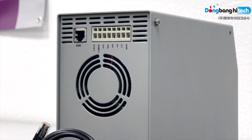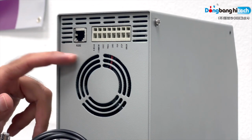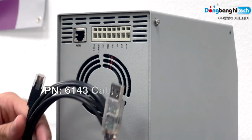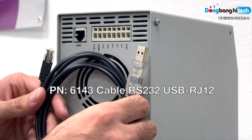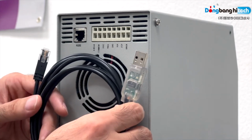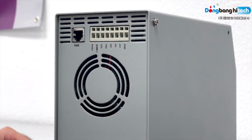If you want to control the pump with serial communication RS-232, we have RJ12 connector in the back panel. We also have this cable that we provide under the part number 6143 from RJ12 to USB. When you are controlling the pump through serial communication, the pump does not send messages